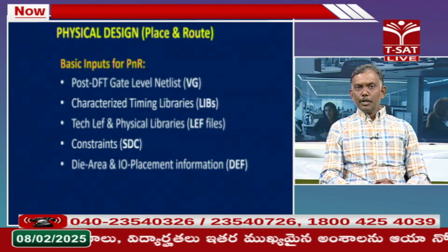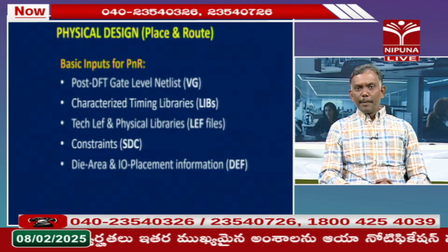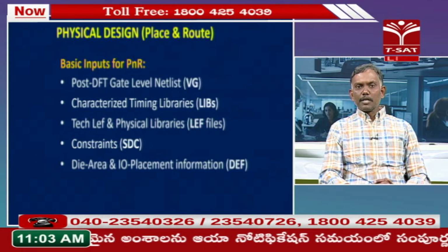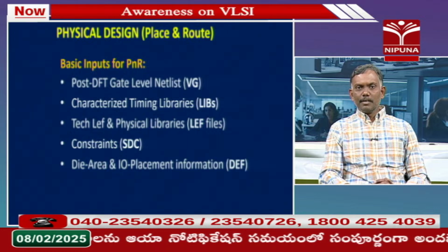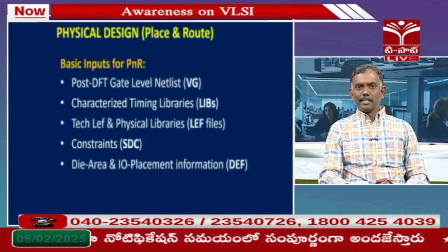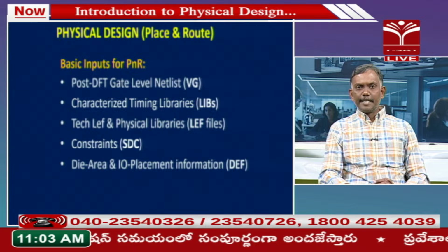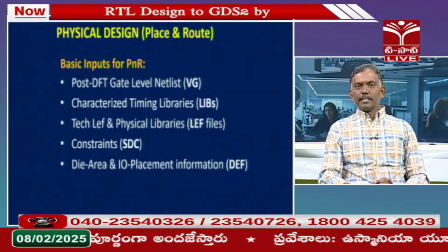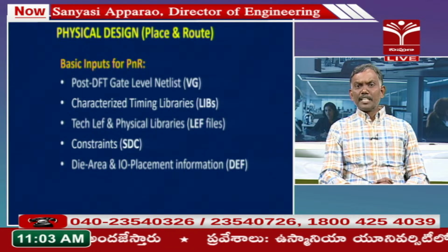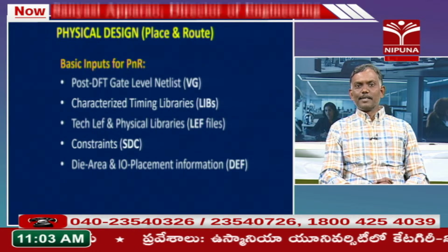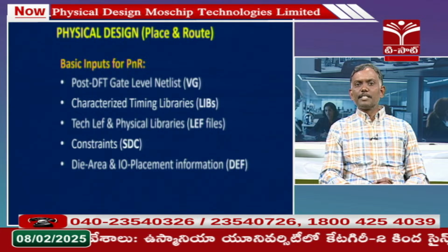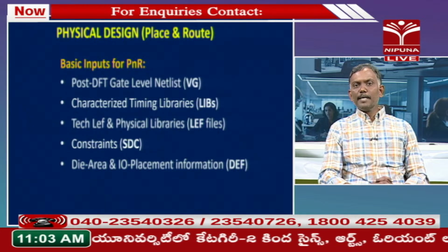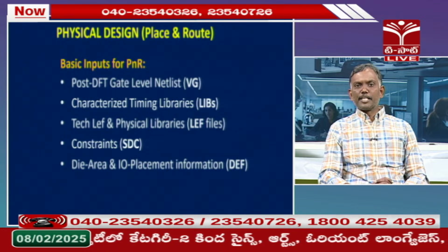If you recollect, IO pads, IPs, standard cells, RAMs, all those are called hard macros. These are predefined cells, right, with a certain width and height, and also pin information. To load our design in the PNR tool, we require these physical libraries for all components present in the design along with the TechLEF. That is one major important input for place and route.